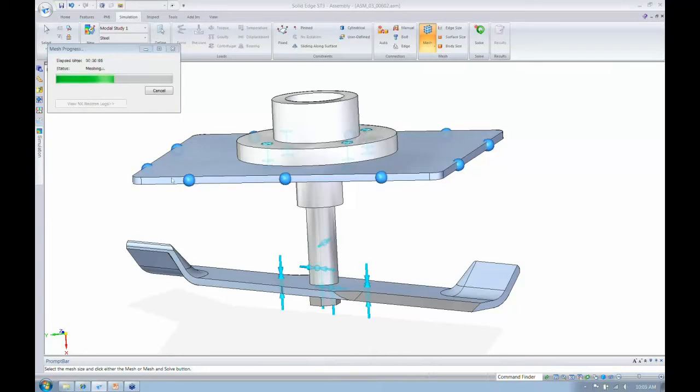I reviewed it already. So what I wanted to talk to you about here is there are 2 types of vibration, free vibration and forced vibration. Like I said, when you ping a tuning fork, that's free vibration. It's just vibrating at its natural frequency or its resonance. And all that means, it's dependent on the mass and stiffness of the part, and at that point, the amplitude of my displacement is going to be very high. So I want to avoid operating in that range.